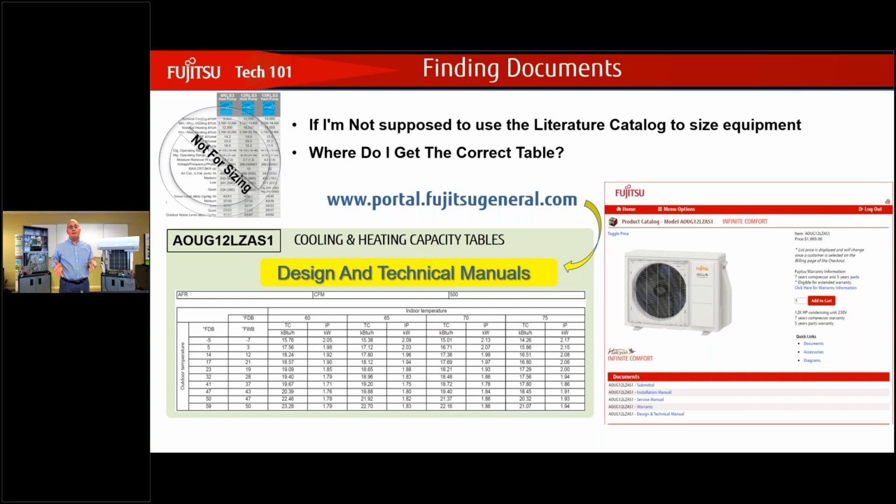If you're not planning on using any type of platform, maybe it's going to be just cooling only, and Mr. and Mrs. Smith think that coil looks ugly, well, pick up the outdoor unit and walk it down a ways, because you have to have the minimum. Rob will tell you, and all of us will tell you, if the minimum's not there, what's going to happen? We're going to kill the compressor before the warranty's out. It's not going to happen right away, but it's going to happen before the warranty runs out.